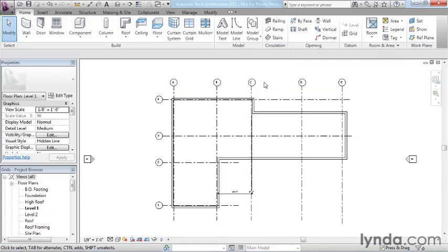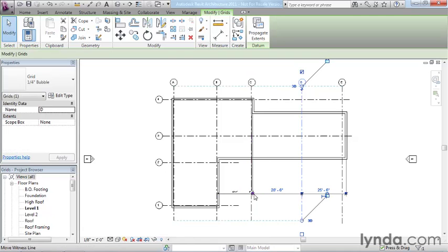And once I have that positioned correctly, I want to put grid line D at 31 foot 8 inches away from grid line C. So I don't want to measure it from the nearby wall, which is what Revit's trying to do. I want to actually measure it from the other grid line. If you click on the little square until it highlights and then start dragging it, okay, so I've still got my mouse pushed in, I've still got it held down, then highlight the nearby grid line and let go, it actually moves it to the grid line, and then I can type this number right here.